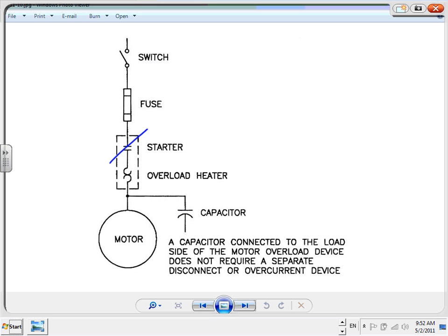And if you have generators with a leading power factor, you have a lot of problems with synchronizing, like we said. Most of the time, 99% of the time, you're going to be lagging, and the best is 94 to 97, not even hitting 100, because if you hit 100 and one load goes down, you move into the leading. So between 94 and 97 is the best correction.